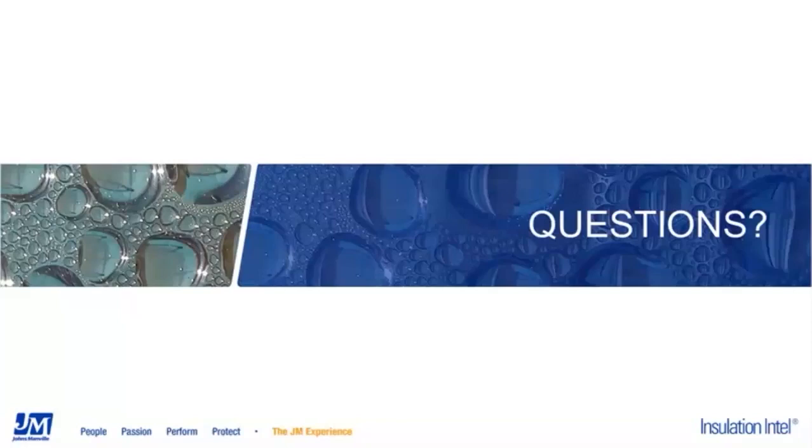And it's still a plastic film, so you also would not do it for physical abuse resistance. You'd want to use PVC or metal for physical abuse resistance. The only reason you'd really be doing it would be to get a better quality vapor retarder than good old ASJ.